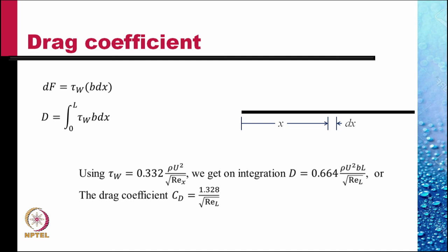The paradox arises on bluff bodies, where though the prediction from inviscid theory applicable for large Reynolds number is still that the drag should be 0, the drag coefficient is of order 1. That is a paradox. How can the drag coefficient be that large?